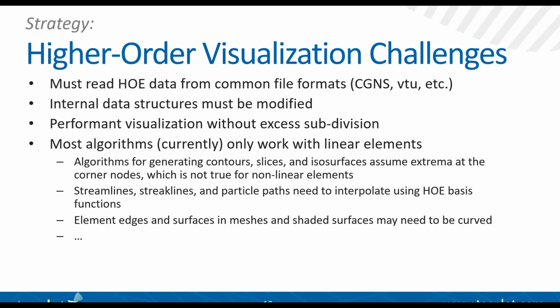An example would be marching cubes, if you're familiar with that. And that's just simply not true for nonlinear elements. You may have extrema anywhere within the element. Could be somewhere in the middle of the element, could be on a face or on an edge. So you can't count on it being at one of the corners.